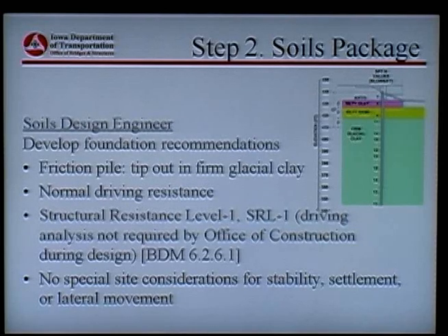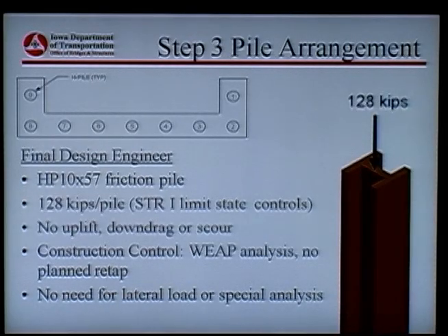We don't have any special concerns about global stability, settlement, or lateral loading. Here's the pile arrangement in the footer for the abutments. Notice we've got 7 piles across on the abutments and 1 pile behind underneath each of the elephant ears here. 128 kips, strength 1, limit state.